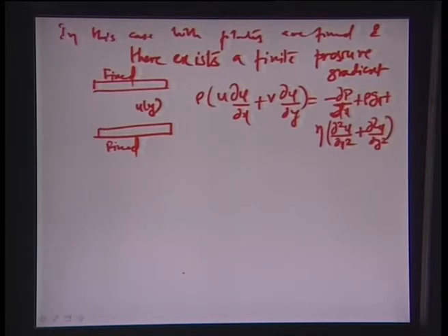Okay. So, from the conservation of mass equation, as we already saw in the earlier slide, ∂u/∂x in that case is 0, right. So, this component is 0, there is actually no v in this particular case, it is again a unidirectional flow, we only assume flow along the x direction. But as you see by the conservation of mass there is no variation in u along x, u only varies in the y direction. Okay. So, there is a finite pressure difference in this case, this is not a zero term, and we assume no inertial effects. So, rho gx is 0.